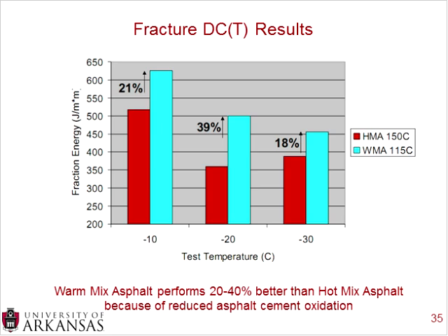And the problem with oxidation is it makes a stiffer asphalt cement binder. So when you mix that with the aggregates and put it in the field, your pavement is already a little aged, because then as time progresses it continues to oxidize and it gets more stiff. But if you can save some of that oxidation in the very first step, then your pavement will hopefully last longer.